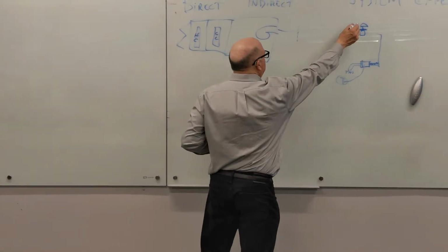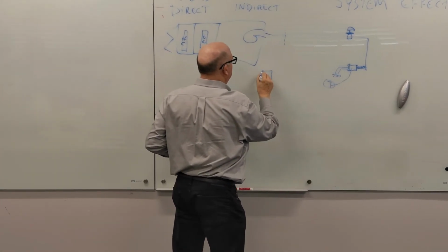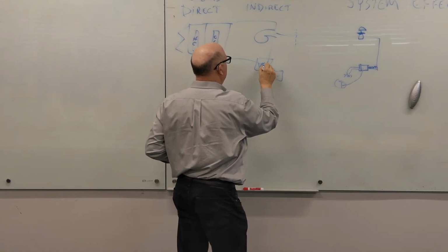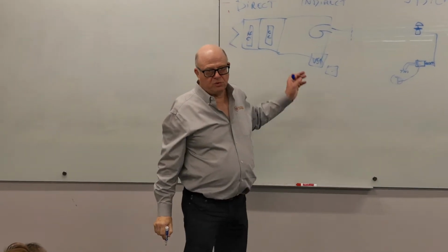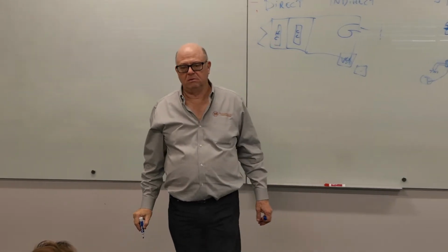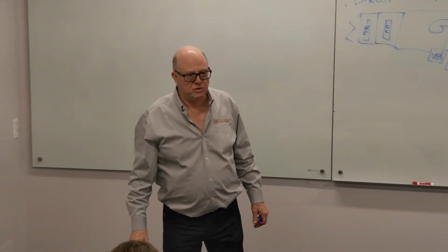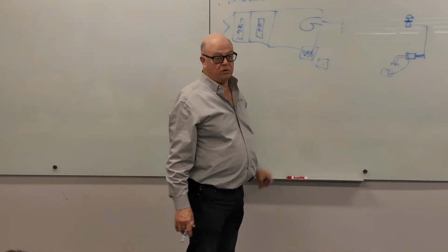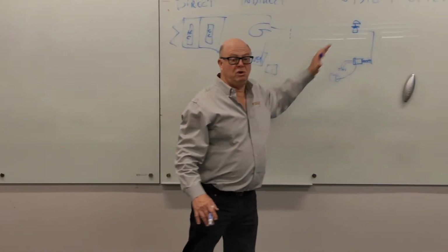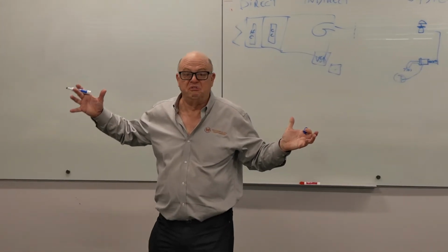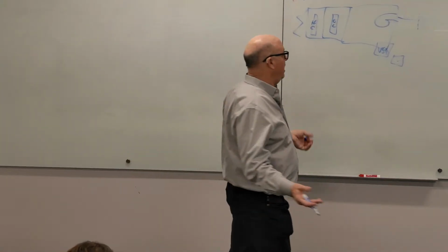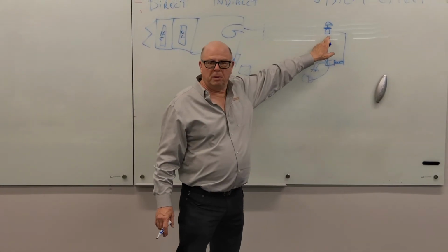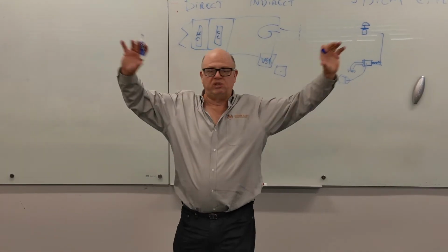And that signal goes back to the controller that tells the variable speed drive what to do. Variable speed drives are pretty remarkable little devices. You can get a variable speed drive with one of those controllers built right in, and you wouldn't even need an external automation system of any sort. You could just have a VSD with a controller and a compatible pressure sensor, and they're their own standalone little thing.